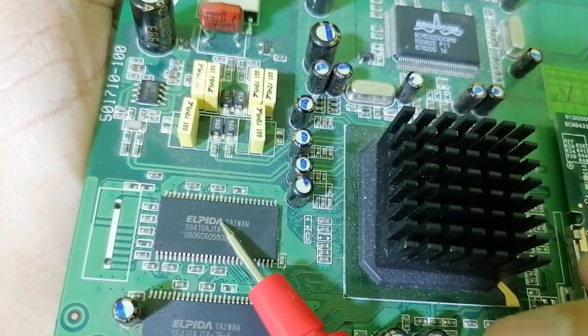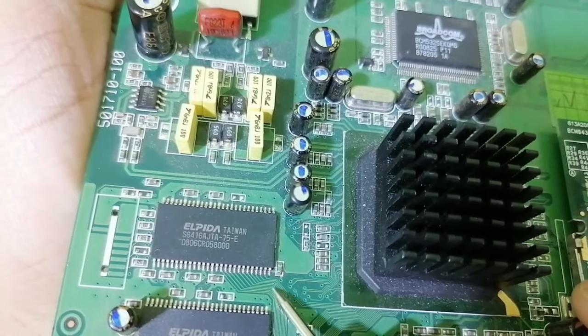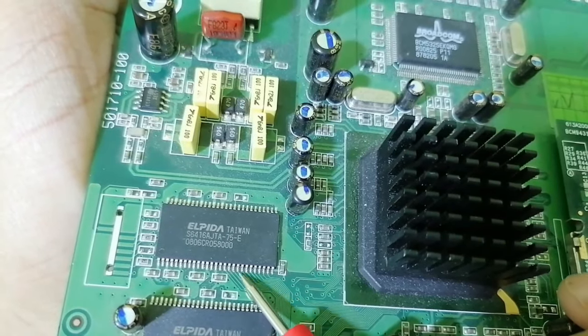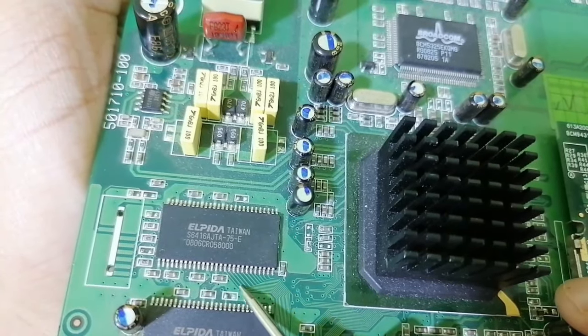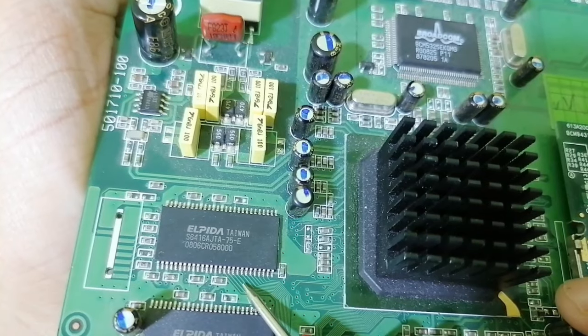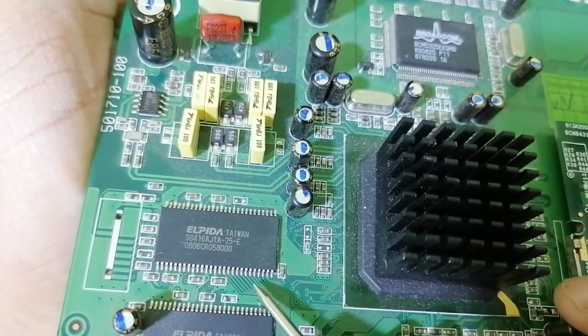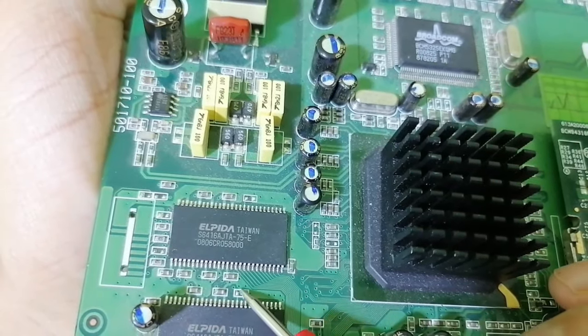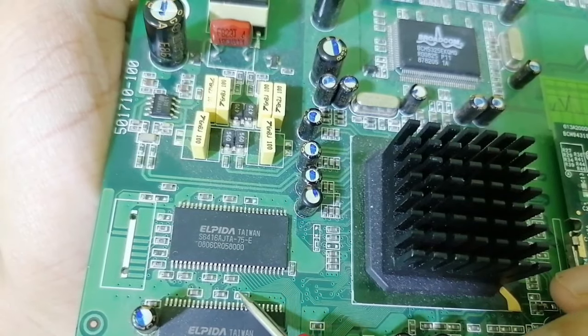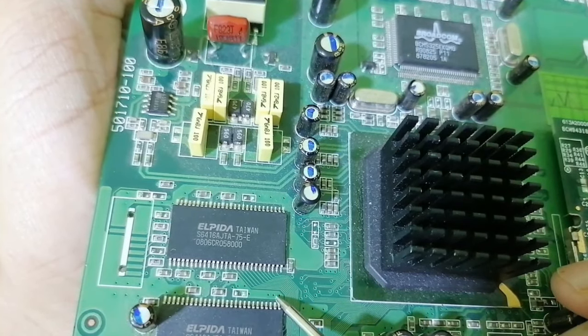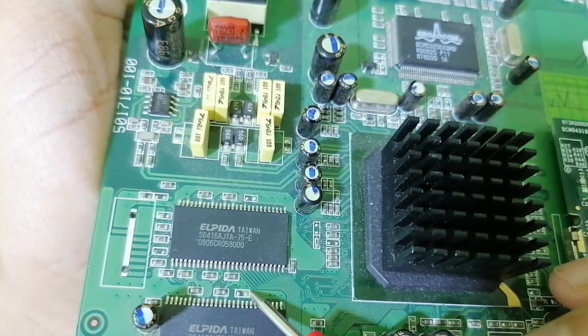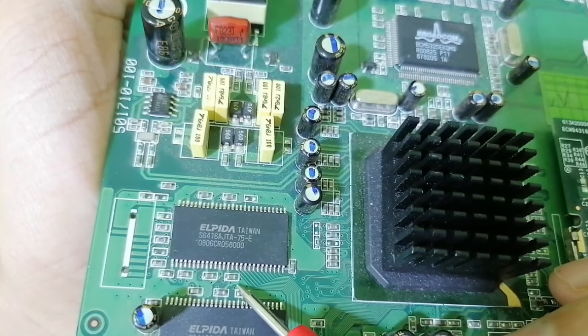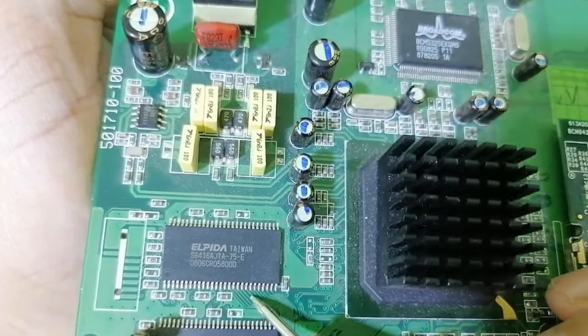So using this method, you can now find the input voltage for every IC without the schematic. Do you see for this IC, for example, here we have many lines and paths. This is basically for control signals. Do you see? The thin lines. And over here we have a very bolded line. This line, as you can see here, is ground. This is not input voltage. This is ground, okay? And over here we have a control signal.